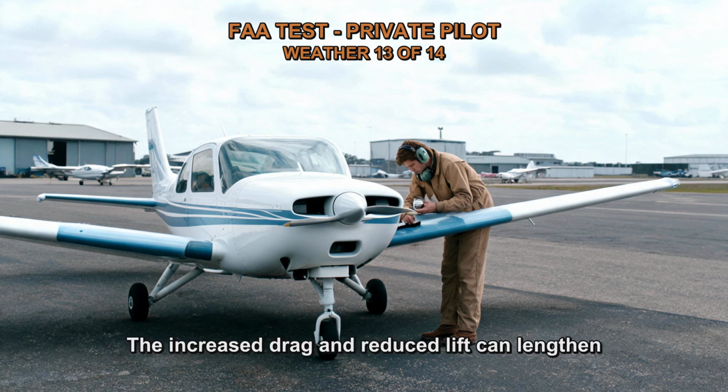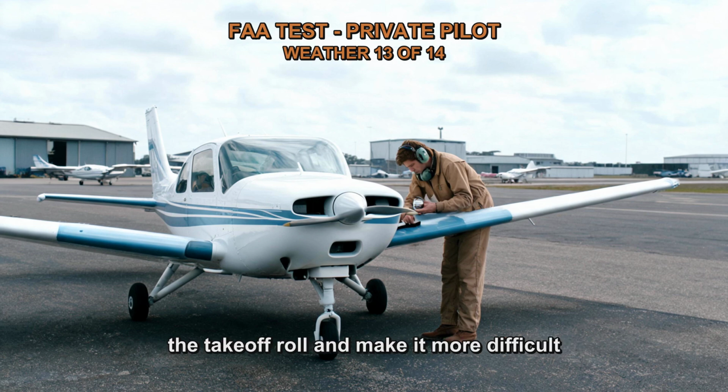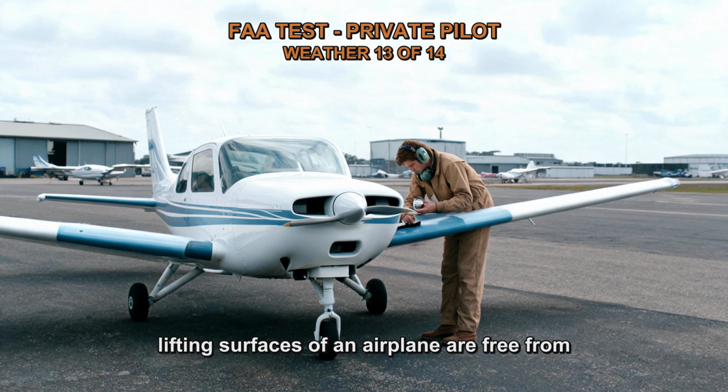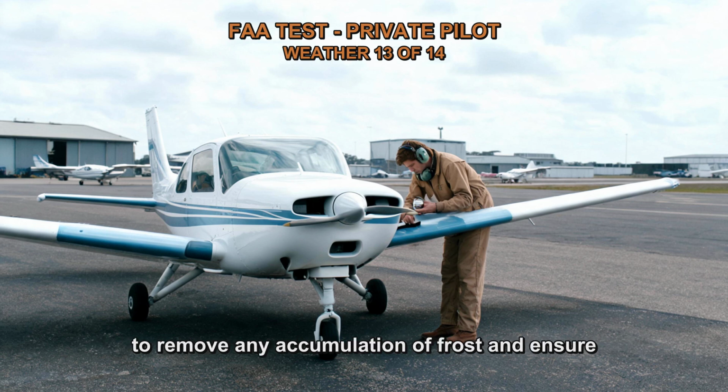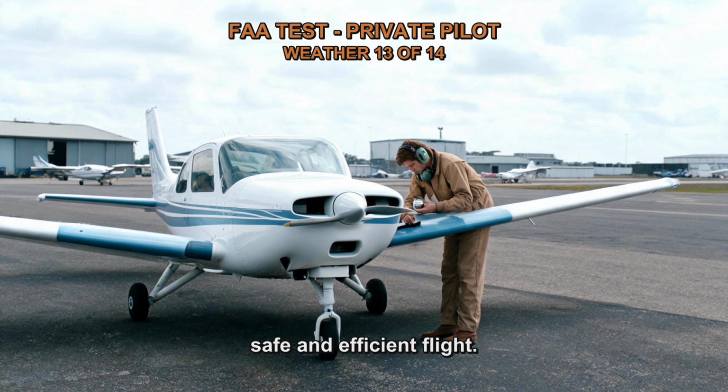The increased drag and reduced lift can lengthen the takeoff roll and make it more difficult for the aircraft to reach the necessary speed for takeoff. Therefore, it is crucial to ensure that the lifting surfaces of an airplane are free from frost and ice before takeoff. Proper de-icing or anti-icing procedures should be followed to remove any accumulation of frost and ensure safe and efficient flight.